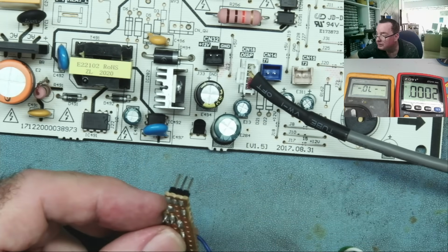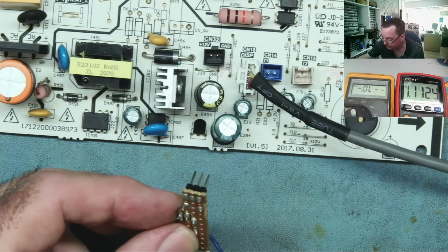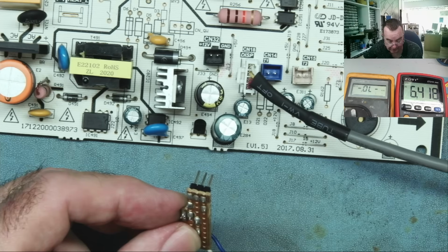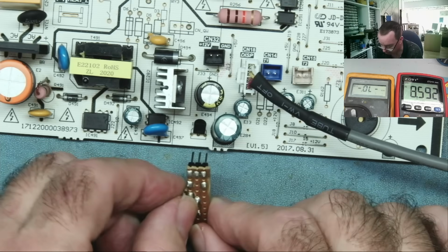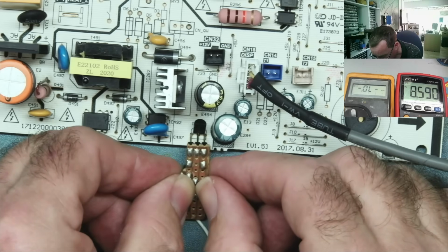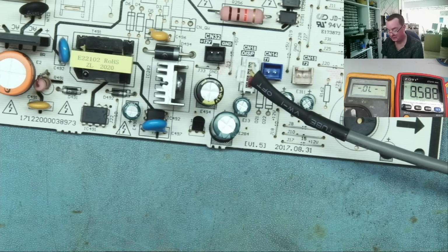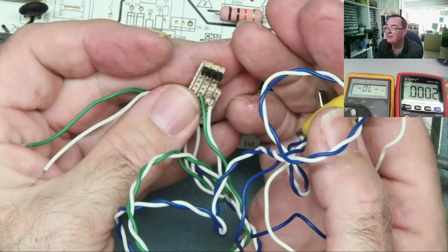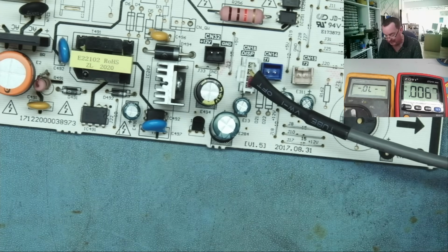Okay, we switch the bench power supply on, and this meter will initially just read whatever voltage the bench supply is at, which is 1 volt. So I'm going to just change it up a bit, doesn't really matter, 5 volts, 9 volts, something like that, okay. And then I connect across the TL431, and if it's good, it'll read 2.5 or very close. Yeah, there, 2.499. So that's good. This thing is extremely useful, guys. You've just seen that, yeah? And it doesn't matter which way round you put it, it'll still give you the same reading, 2.5.